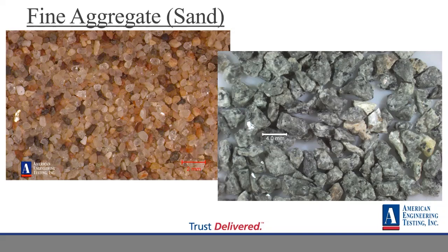So the number 4 and number 8, you can typically do that as a hand sample underneath our stereoscope. Otherwise, we do make thin sections of everything passing the number 8. And when you're looking at the thin section for sand, you try and get a point count of 150 particles and no rock descriptions, but what you're just doing is taking a tally.